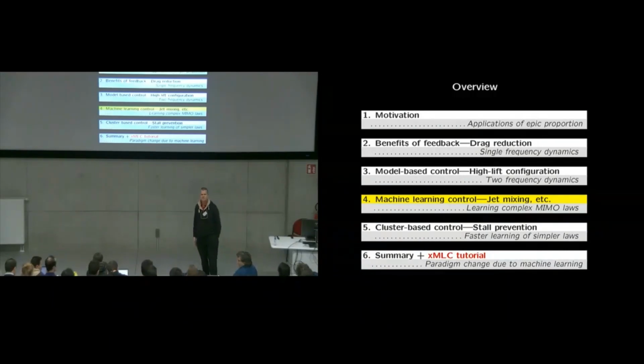But you didn't identify them by POD? Well, you can take the first 2 modes as POD, the second 2 modes as POD, and the other, the shift modes, need to be identified in a different method. These are empirical modes, yes, and they are effectively a POD mode if you look at the right transient, if you process them in the right way.